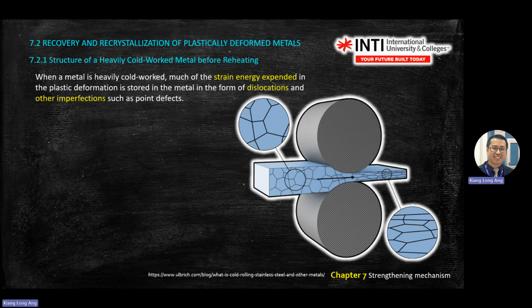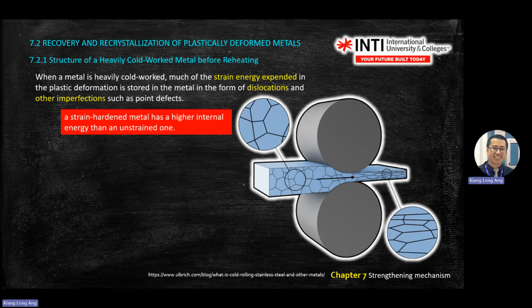So this is cold rolling. Cold rolling means you put the metals through a roller and it presses on the metals. When you're pressing, you are strengthening the metals. So you see the microstructure become more and more dense when you roll it. When you have a defect or a space or void there, you squeeze the metal particles together and actually eliminate the space. So when you do cold work, you're actually reducing the gap or void.